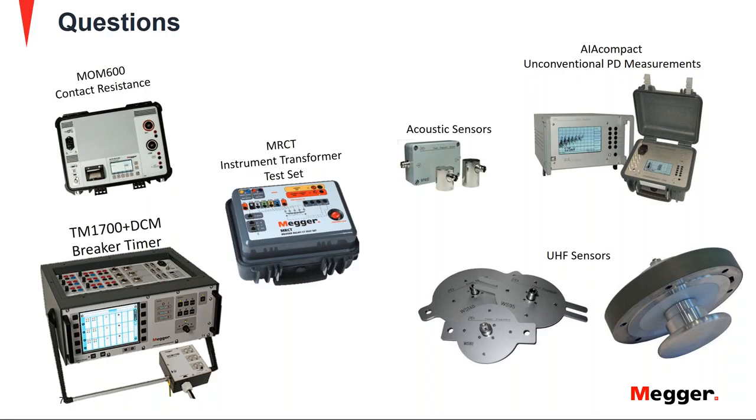You mentioned first trip as a test for the circuit breaker. What is first trip test, and can I measure breaker timing with this test? Okay, yeah, we didn't cover that technique in this presentation. We have other presentations that talk about the first trip, but in summary, first trip is a test that measures specifically the current of the tripping coil after the breaker has been in closed position for a long time.